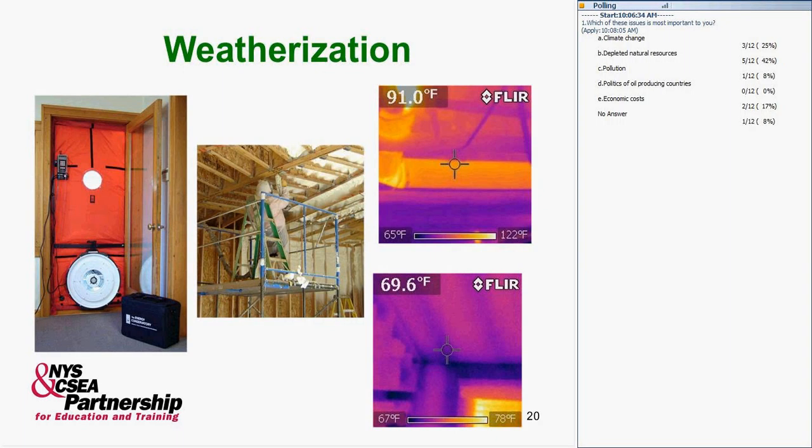Okay, now, weatherization. Some of you have probably seen this tool here. It's called a blower door. Basically, we fan in a door, we pressurize the building, and we tell how bad the drafts are. It's become really commonplace. It's actually becoming part of the building code.